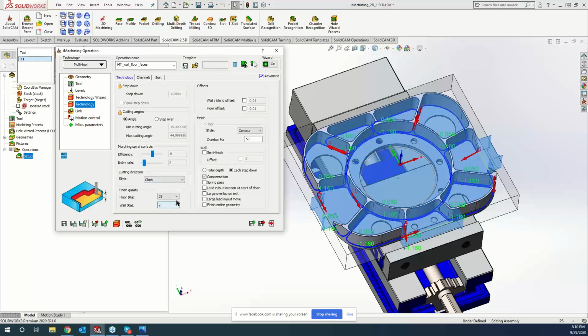So let's say Tim's got on his print a RA finish callout of 63. I would just bump it back 1, so we can just tell it a 32 RA finish. That way we know for sure that we're going to get that finish that we're looking for in there. That's like a perfect world condition type value is what we're going off of there. Okay, gotcha. Yep. And as we all know, we love that perfect world, and it never happens.